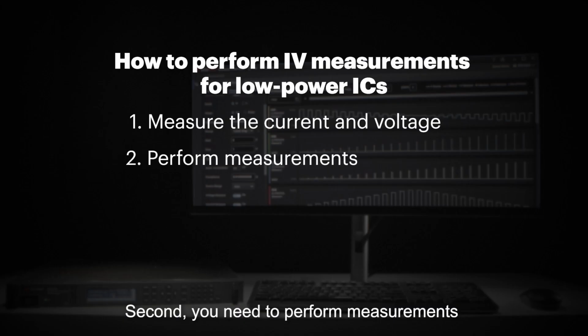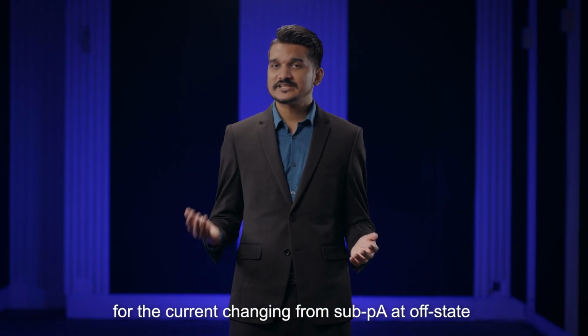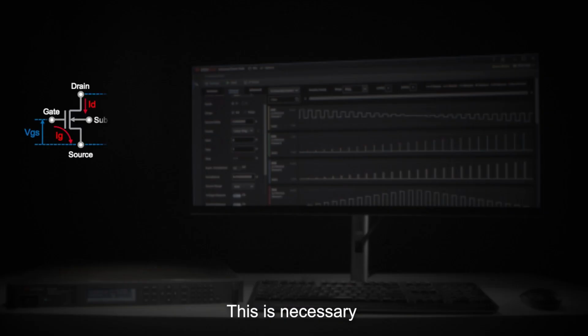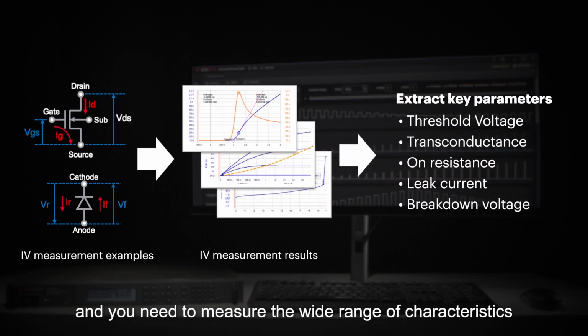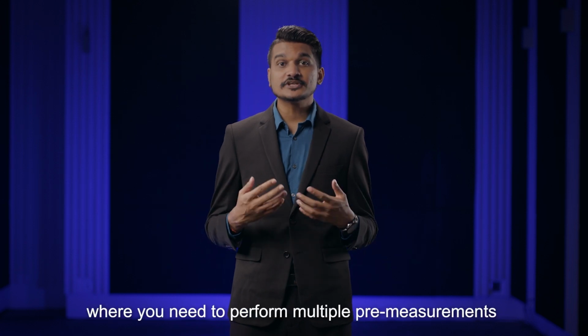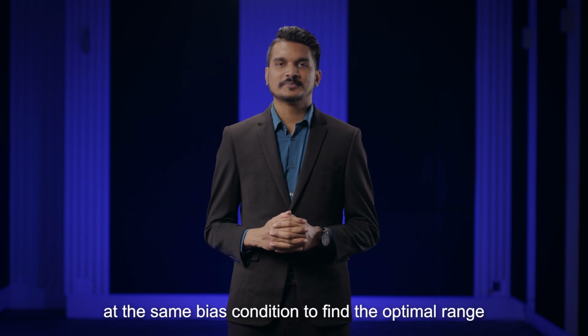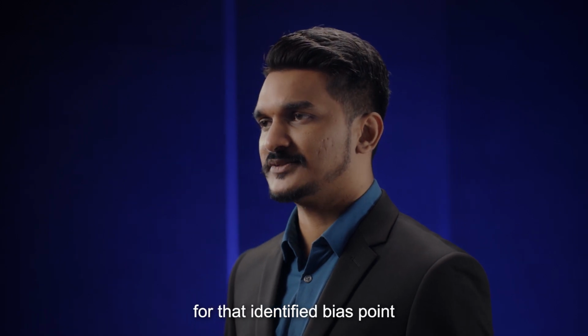Second, you need to perform measurements at various positive and negative bias conditions, while covering the wide dynamic range for the current changing from sub-picoamperes at off state to above milliamperes at on state. This is necessary as low power ICs have bipolar characteristics, and you need to measure the wide range of characteristics while sweeping and stepping through the bias conditions. There could even be cases where you need to perform multiple pre-measurements at the same bias condition to find the optimal range. Then, perform the measurement at the optimal range for that identified bias point.